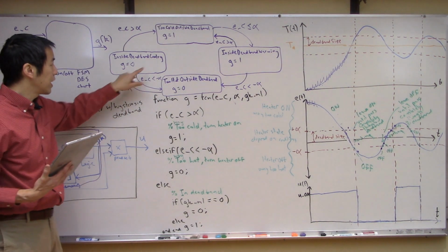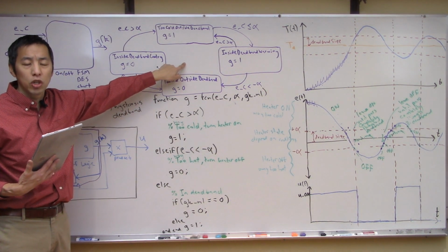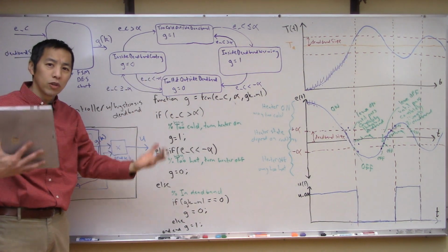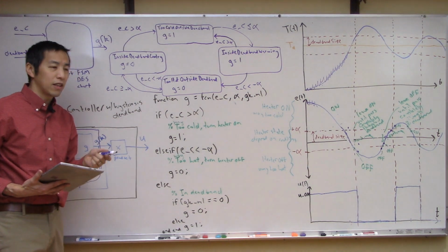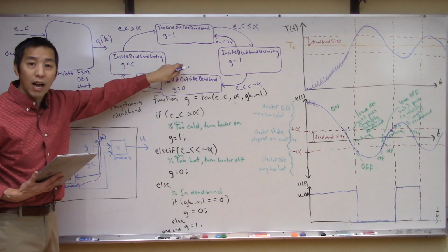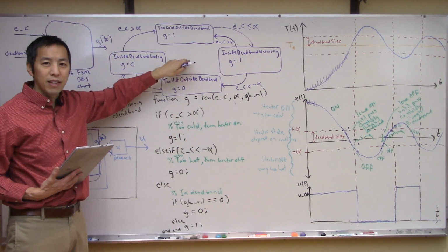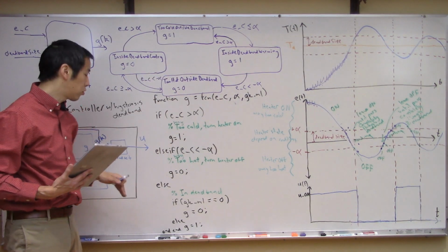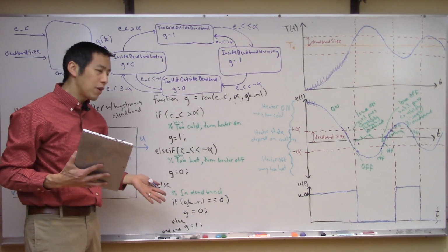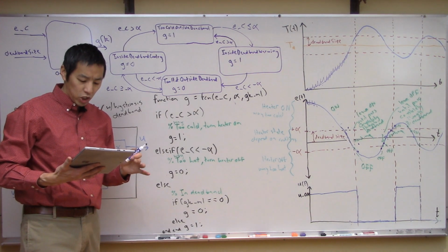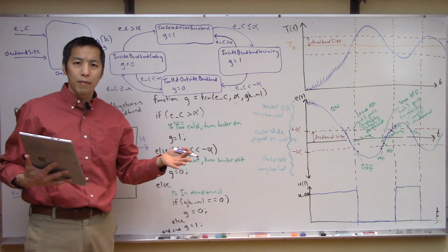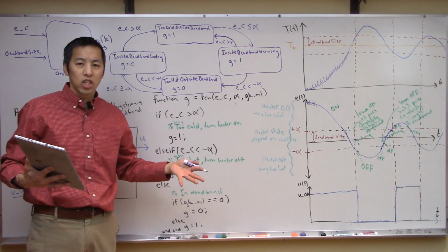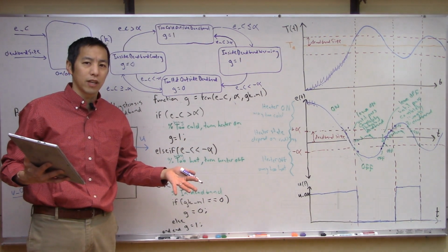And again, I just like this finite state machine representation a lot more. I think it's more intuitive. I can understand it a little bit better. And the fun thing is, we're going to see in just a second that Simulink has a nice package that's going to allow us to directly implement this kind of logic within your Simulink model. So with that being said, I think we've got all the ideas down. Let's just go over to MATLAB Simulink and build a simulation of this to just verify that this all checks out.